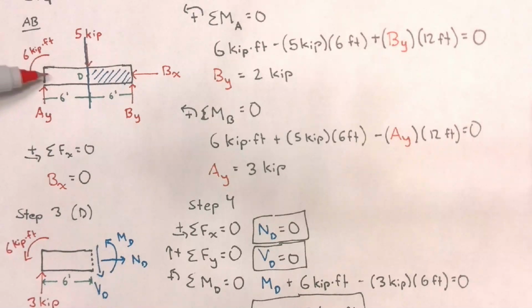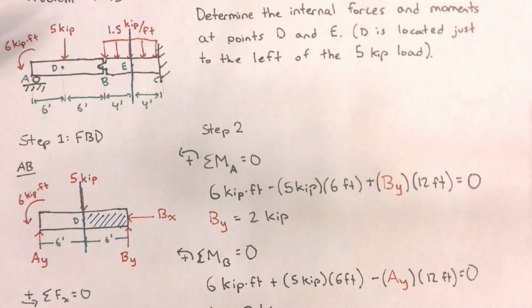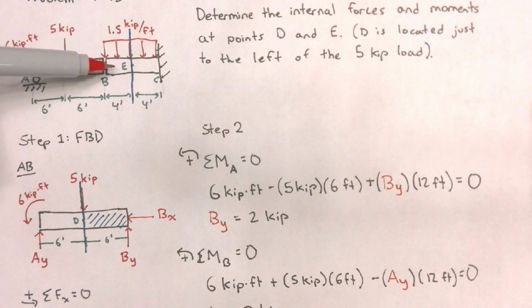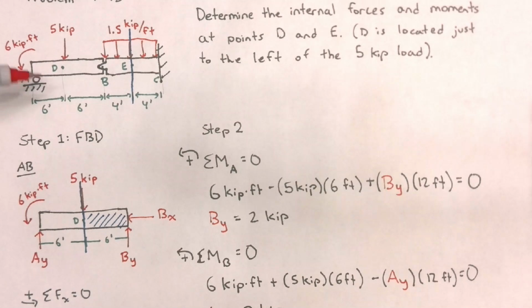On my member AB, my hinge reaction was positive, pointing upwards. That is because applying these forces would have caused this member to experience a force pushing upwards to keep it balanced. Since this member BC is connected to AB, the force that the hinge will experience at BC is going to have the opposite direction than the force that the member experiences at AB.